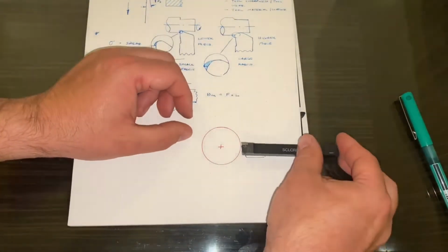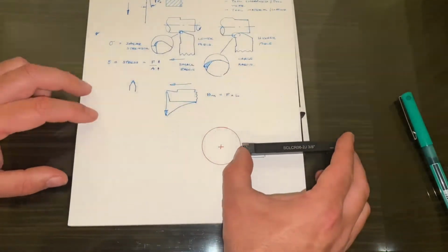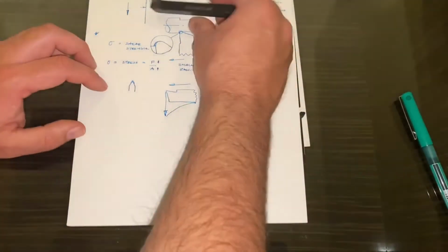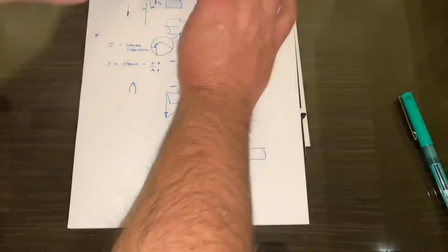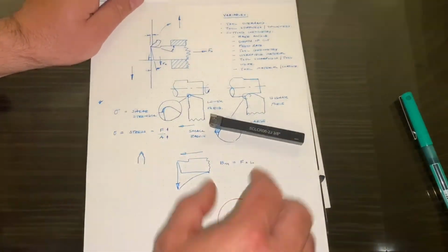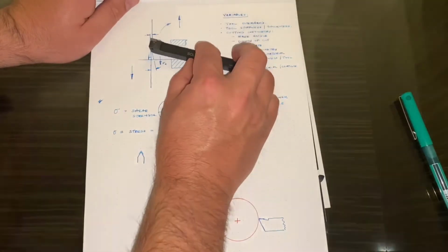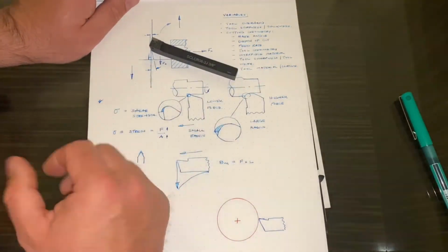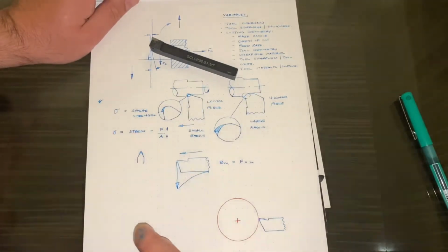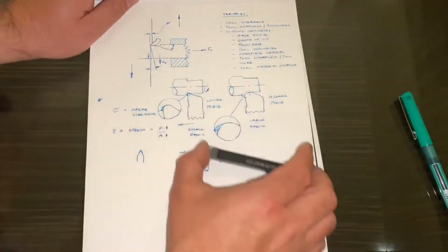But what can happen, there's two things. If the tool is too high above the centre, then that's the equivalent of leaning the tool upwards like this, and we don't get efficient machining because our clearance face is now coming into contact with the workpiece.